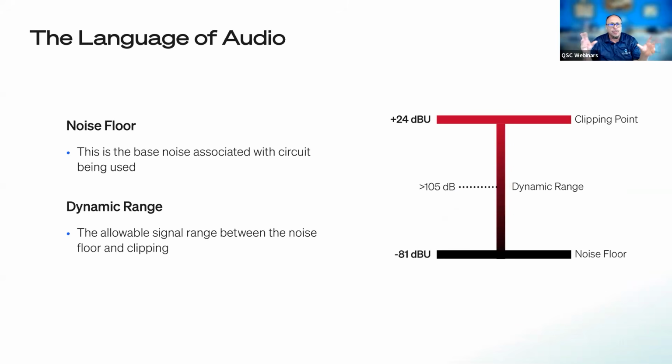One of the things we want to talk about starting off, looking at this chart, is things like dBu. That is decibels. Decibels are always standalone, but they have to be referenced to something. So dBu is referenced to 0.775 volts. A 0.775 volt signal is what we're doing.